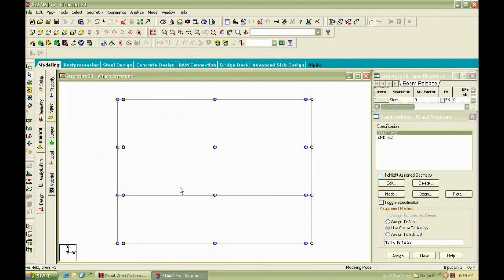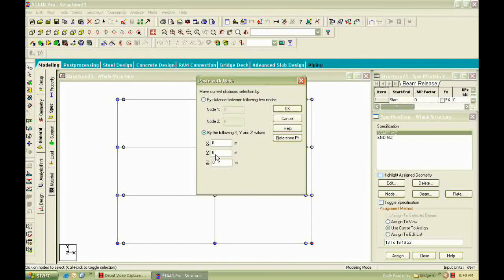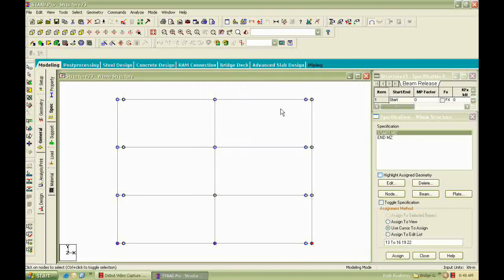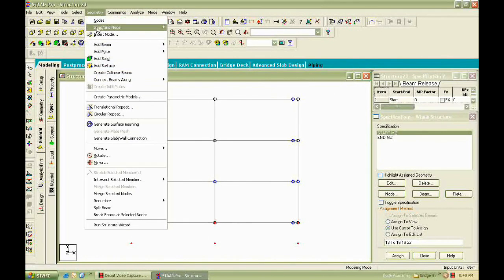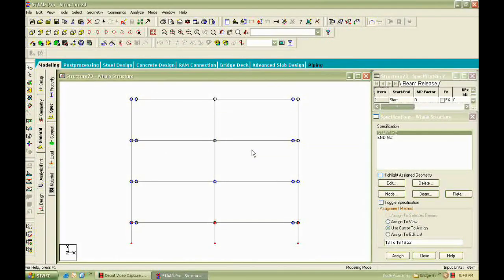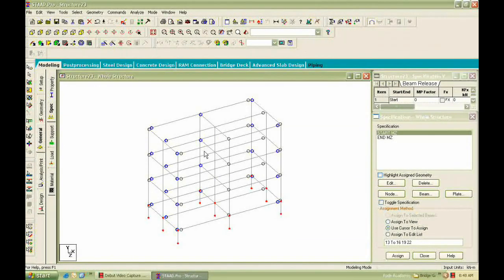That's it. The thing left over is, you can select all the nodes at ground floor, copy, paste, -1.5 for our foundation. Nodes are generated. Now select all these nodes, geometry, connect beams along y-axis. 9 columns are generated. You can see the 3D model of our structure.